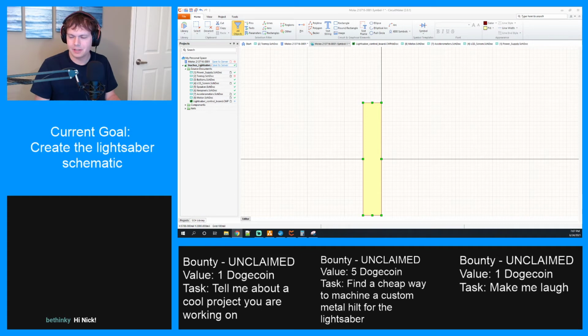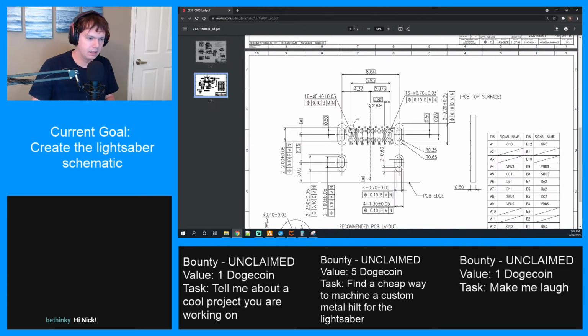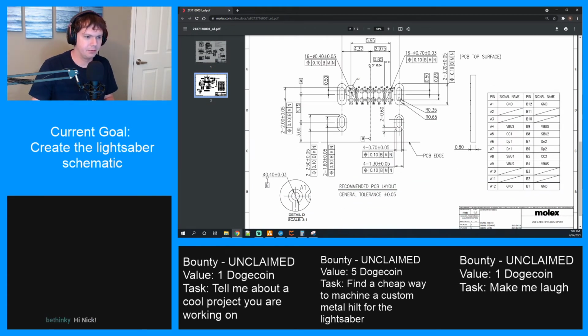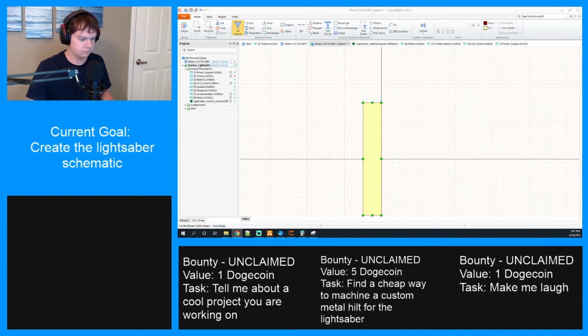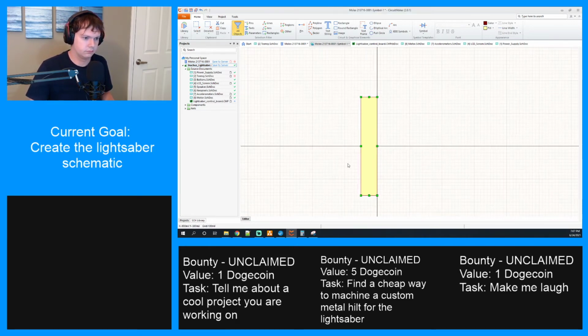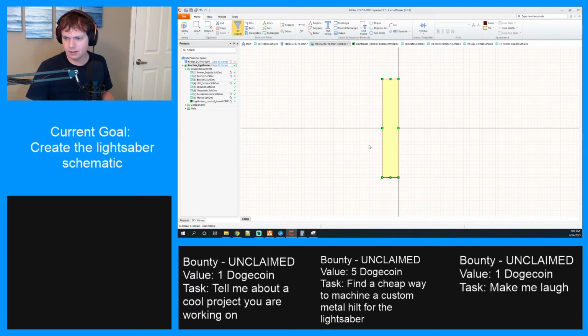Because of the whole thing that we can't have things with the same designators, but these big slots right here, I believe, need to be grounded as well because they're the outer casing, which is also metal. So we're going to have to basically make a ground pin for each of those, and then a ground for the actual ground pins on the inside, which there's 4 of.